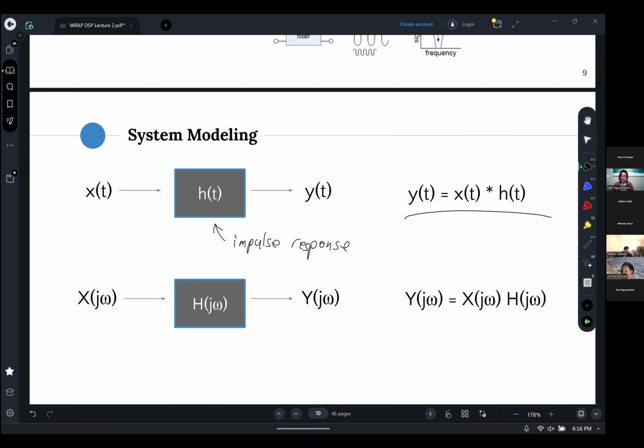So for example, if I have a signal like this, and then I convolve it with just a straight up rectangle, it's going to smooth it out, because the convolving here is kind of just like taking the average of the signal. So that's going to give me something similar to, I don't know, something like this.